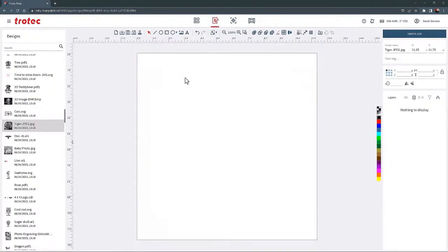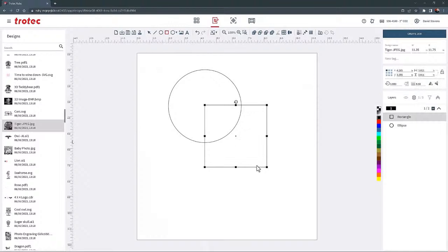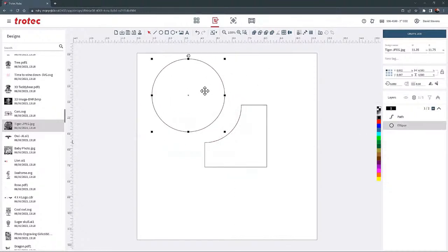The next tool is the difference tool, which works the same way as the intersection tool, by selecting the object, then selecting the letter C on your computer's keyboard. And that will turn that selection into a dashed line. Then select both objects and select the difference tool button. This will clip out the selection of that drawing.